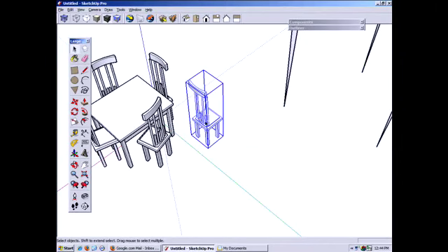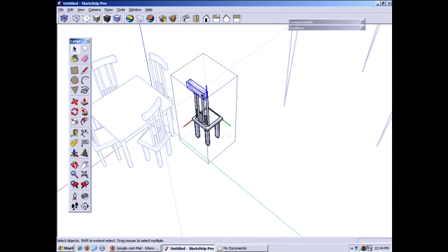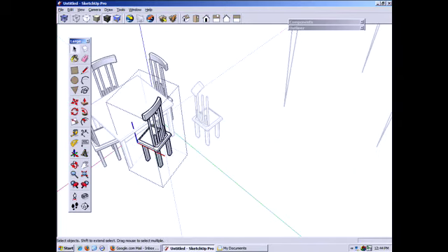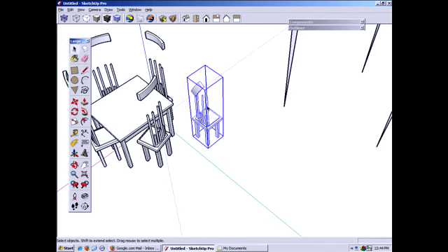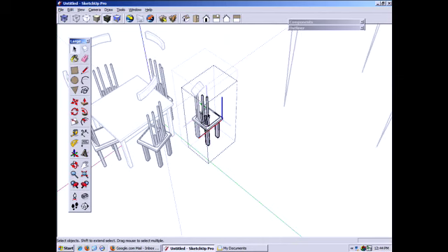So the question was, if we make this large component unique, then if we came in, this guy right here that is buried one level inside, that we move, well, we can change that differently. However, as we know, these guys, they're not. If we dig in deeper to the next level, now we've gotten to components that we haven't made unique. So making unique doesn't translate down through your hierarchy. It only makes unique the level that you're working at. If that makes sense. There was a question back here.